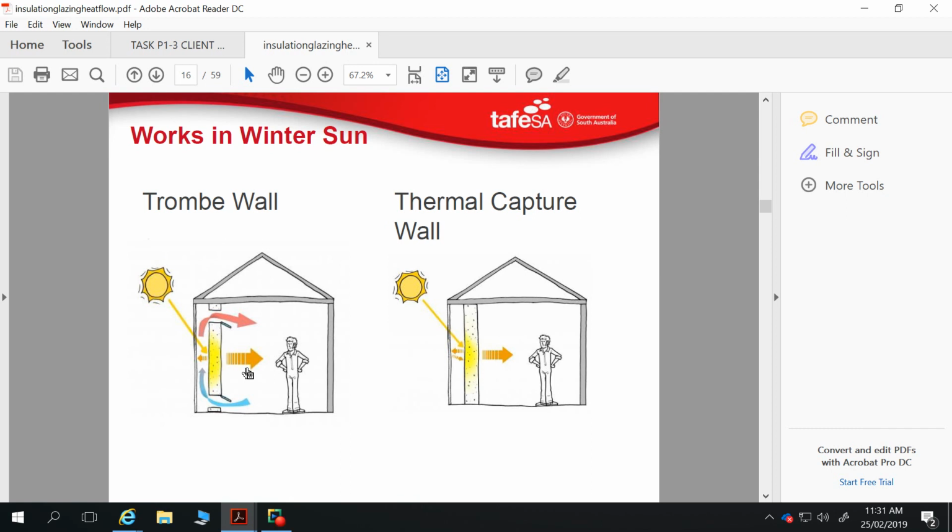For something like this, one of the difficulties is you're not going to have your standard slab underneath. If you're imposing a massive point load on a building at that point, you're probably going to want to have a footing beam running underneath that. But then if that roof is taking your roof load and so on, yes, you can redesign a slab to have a substantial beam there, and then you may only need a very small external beam. I know that's up to the engineers to work out.